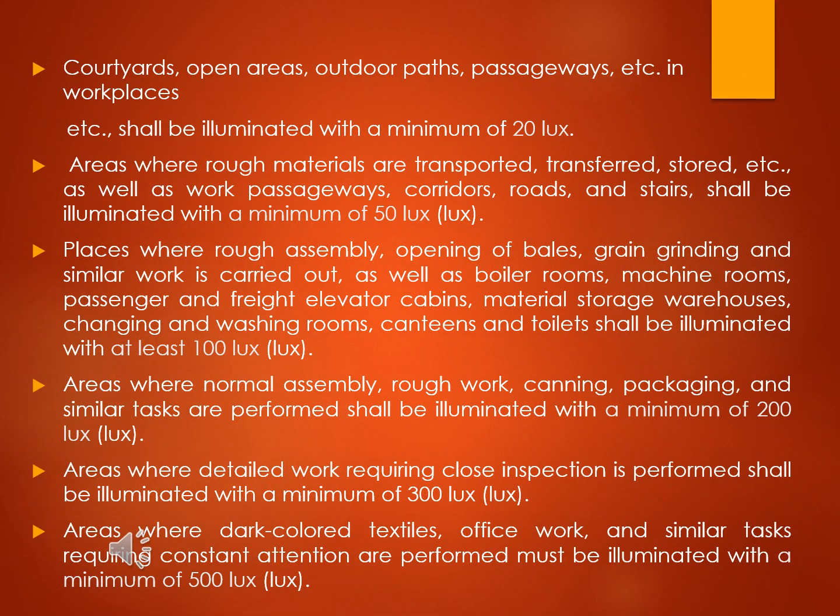Courtyards, open areas, outdoor paths, passageways, etc. in workplaces shall be illuminated with a minimum of 20 lux. Areas where rough materials are transported, transferred, stored, etc., as well as work passageways, corridors, roads, and stairs shall be illuminated with a minimum of 50 lux.